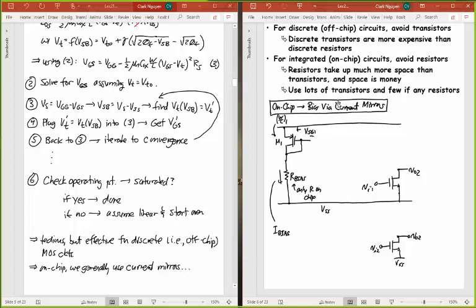I bias, is going to just be equal to the voltage difference. It's going to be VDD minus VGS1 minus VSS divided by that bias resistor. So see, I'm generating that current exactly the same way that I did in that other circuit. But I'm now doing it with this transistor where I've tied its gate and its drain together to create a very specific voltage. The voltage here, VSG1, is the same as the voltage drop between the source and drain.